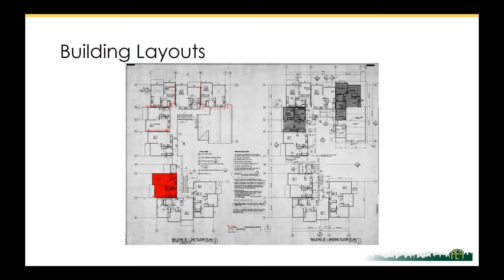This is actually interesting because we determined it would be the worst case unit because it has the most exterior surface area, wall, roof. Below it is a unit. And so it has the most exterior surface area. However, when I actually modeled the entire second floor of this property, hopefully you can see my mouse, the unit above was determined to be the worst case unit, even though it had all these south facing windows.